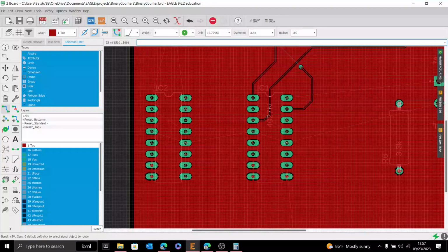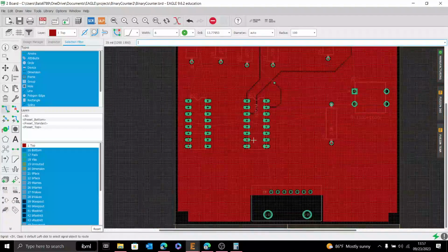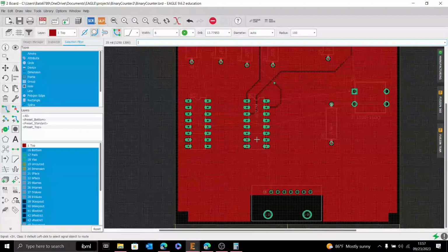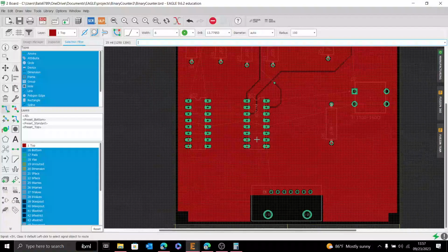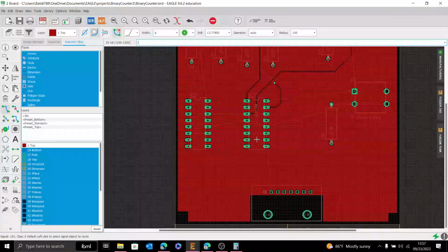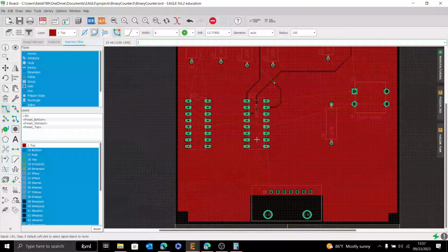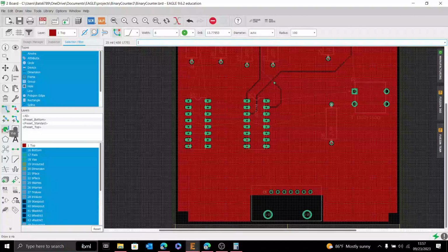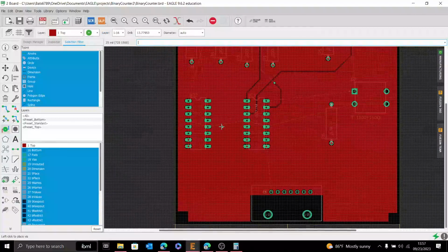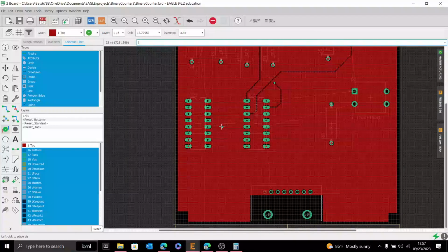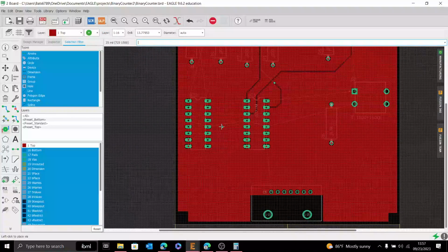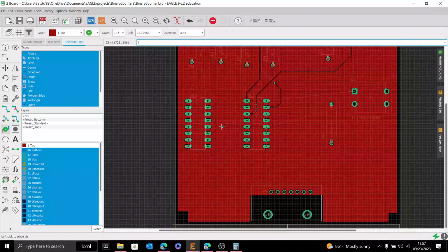But could you imagine that we could get the wires in such a way that we effectively form a box, and then that plane is no longer attached to the rest of the plane? Can we all imagine that? So a good idea is that if you're doing a 2-layer board with a plane, you would also want to put the plane on the bottom. And then everywhere you have isolated planes, you would stick these little vias so that they're connected, and that whole plane is a ground plane instead of just a sheet of floating copper, basically. Make sense?